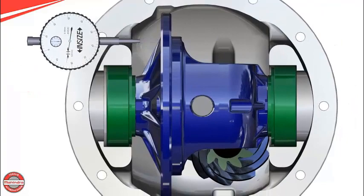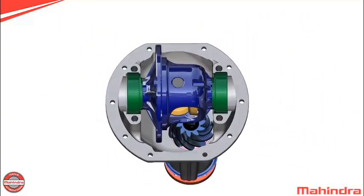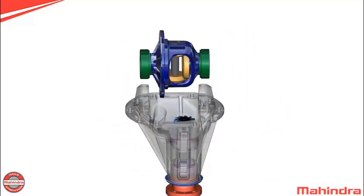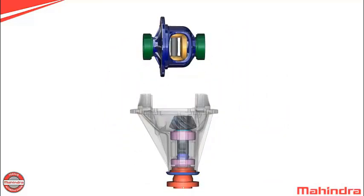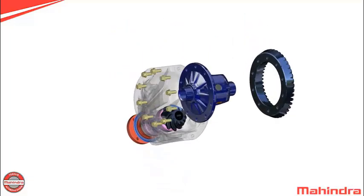Remove dial indicator. Remove differential assembly from housing. Remove dummy bearings. Assemble ring gear to differential case.